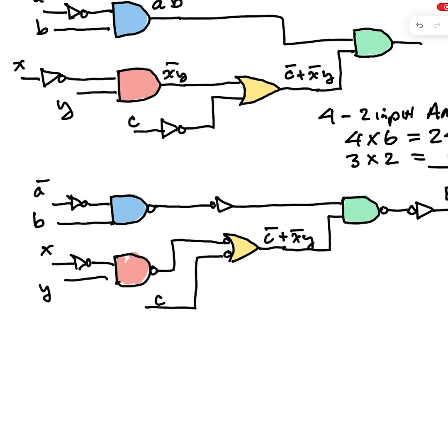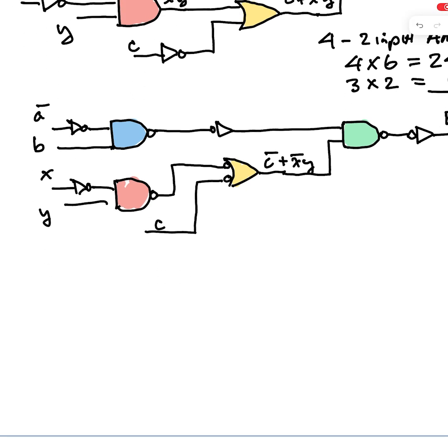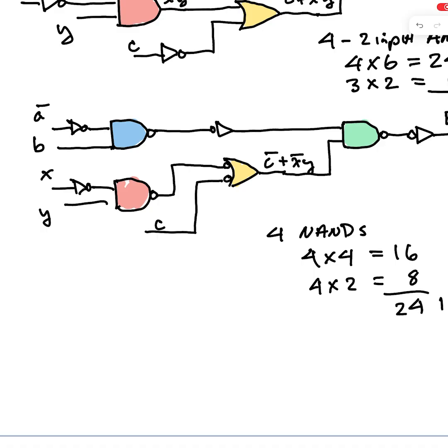Okay, so down here on the all-NAND, what I see is 4 NAND gates, and each of those takes 4 transistors, so 4 times 4, we now have 16. That's where the savings comes. All right, but it does turn out that we had to have an extra inverter to make this all work out. So that's 4 times 2 transistors for each inversion, so 8. But we do see a savings of 6 transistors if you implement things this way.